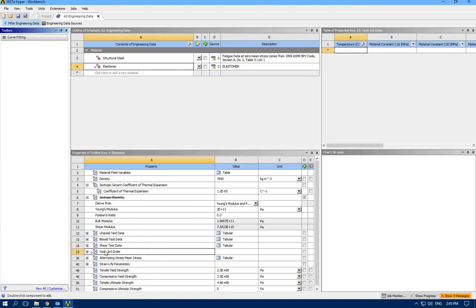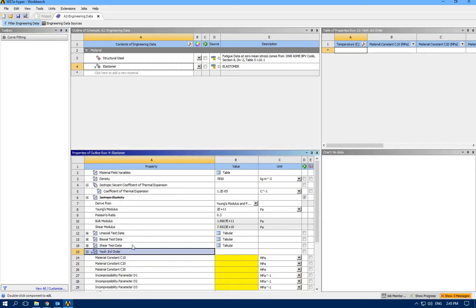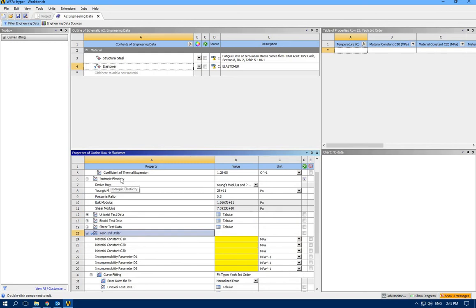By including this model, ANSYS is automatically going to get rid of isotropic elasticity, because by adding this we are going to have hyperelastic materials, and this Young's modulus or Poisson's ratio is not going to be one number. So ANSYS understands that and says, okay, you are going for the more complex material, so that isotropic elasticity option is not going to be valid anymore.